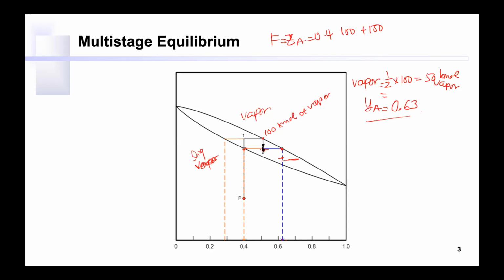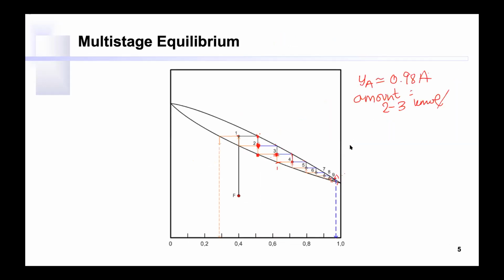So we cooled it down a little bit up to here, and what we can do is just wait, and then it's going to separate into phases again. Now, instead of putting a fan or a heat exchanger to cool it down, we actually use the reflux, or a liquid from somewhere here, to cool it down.